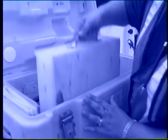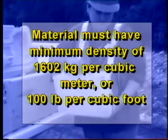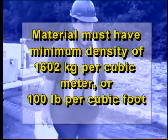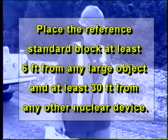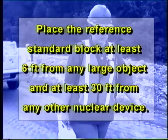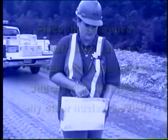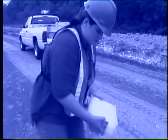Place the reference standard block on the compacted material that has a minimum density of 1,602 kilograms per cubic meter, or 100 pounds per cubic foot, that is at least 1.8 meters or 6 feet from any large object, including vehicles, and at least 9 meters or 30 feet from any other nuclear device. The operator should stand away from the device when taking the standard count.